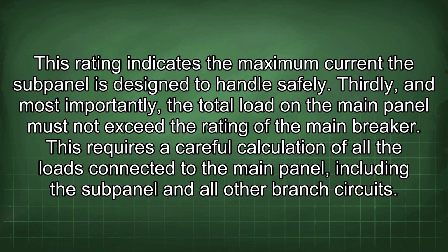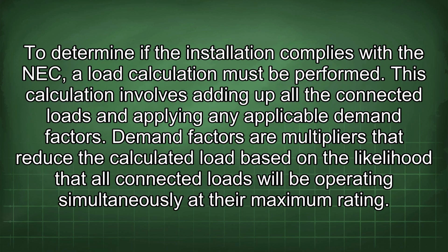Thirdly, and most importantly, the total load in the main panel must not exceed the rating of the main breaker. This requires a careful calculation of all the loads connected to the main panel, including the subpanel and all other branch circuits. To determine if the installation complies with the NEC, a load calculation must be performed.